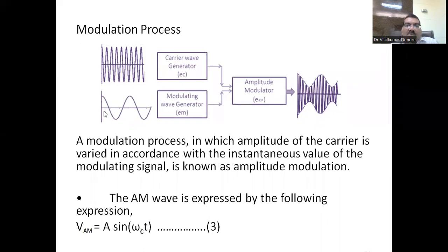But it is not put simply. If it is put just like this, it is difficult to put the high frequency signal in between. So what is done? This signal is taken and it is given a DC offset. Taking it a little higher, a signal is generated above and it is also generated below. So this is the actual signal, this one with some DC offset here, and this is the replica of your modulating signal, the mirror image. Now can anybody tell me whatever this waveform I am showing, whether it is under modulation, over modulation or perfect modulation, and why?